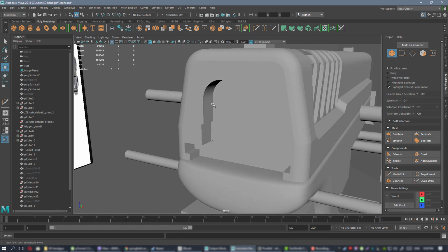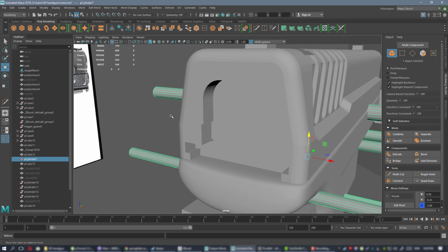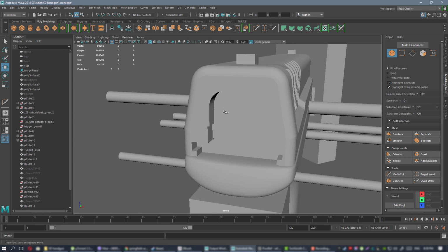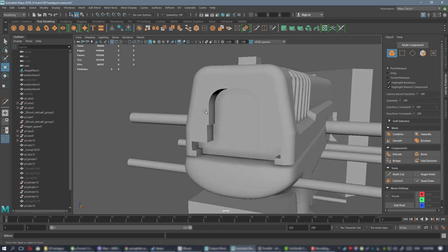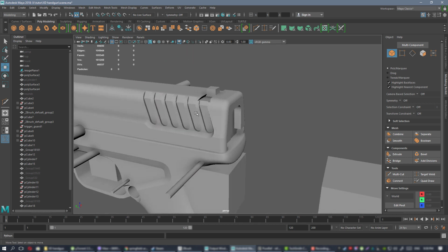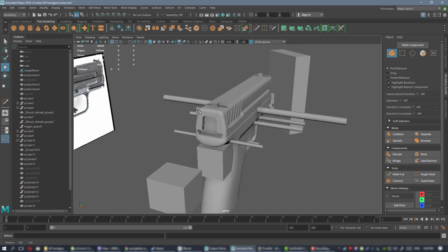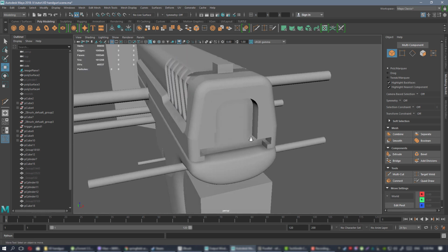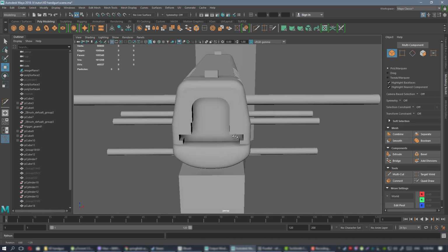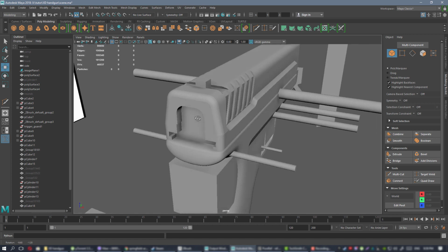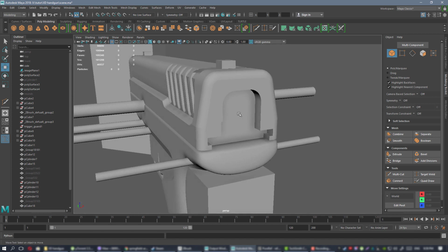So what I was saying, as we can see here, the edges are so sharp, so it's kind of hard sometimes to navigate across this scene. So what you can do is turn on the ambient occlusion of the scene. That will shade the internals and the places where the transition from surfaces happens. So it works basically like ambient occlusion in any engine or Marmoset. So now it's easier to indicate where a surface ends and a new surface starts.